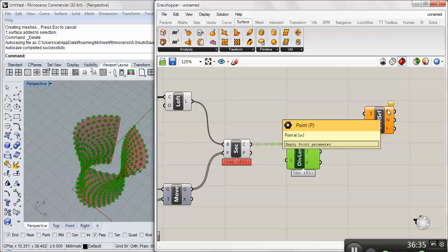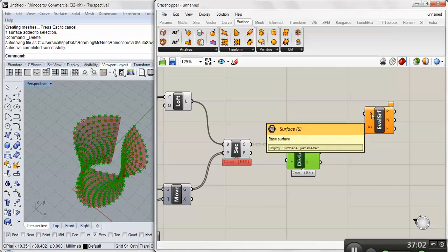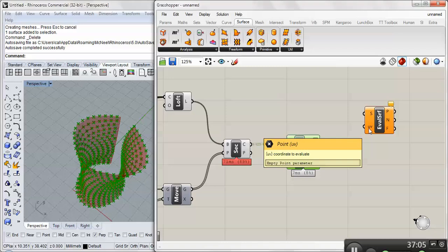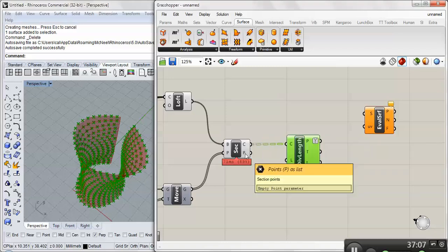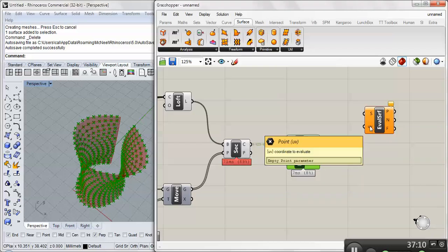But all of these have this UV after it. The concept of UV is just a local coordinate system for every surface. The way it does its own internal tracking of the topology is it gives all these surfaces this sort of pseudo coordinate system. It's not something that has units. It's independent of units. So in this case, what it's asking for is a surface and a UV coordinate. All our coordinates are in normal space. We have x, y, z's. UV would be that point on the surface, the UV point.